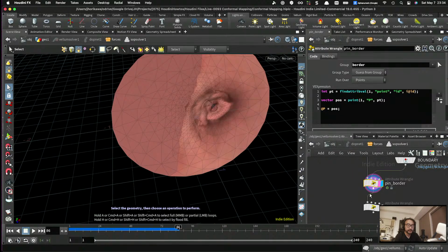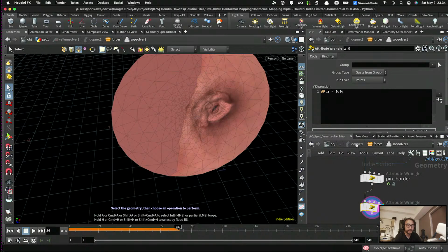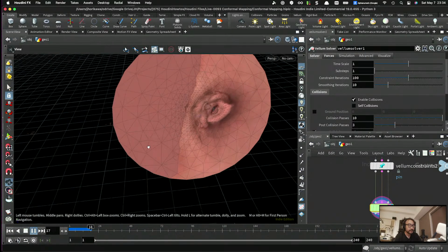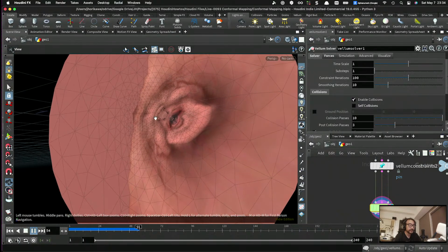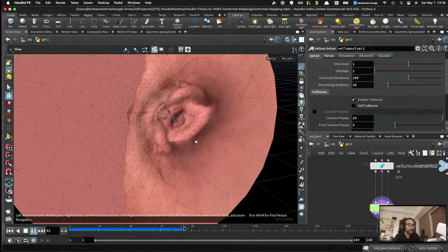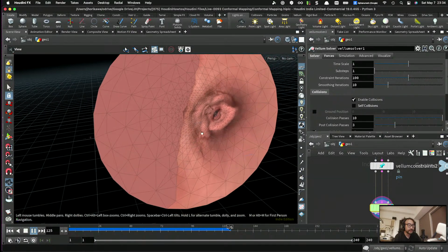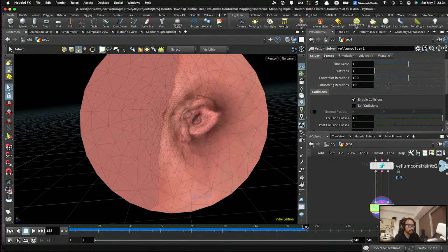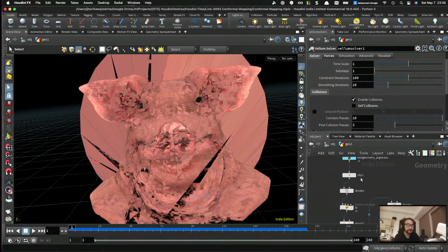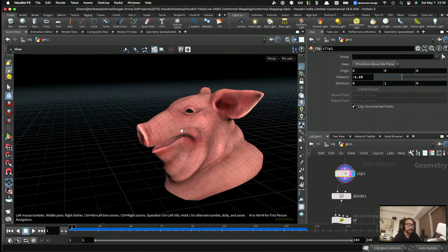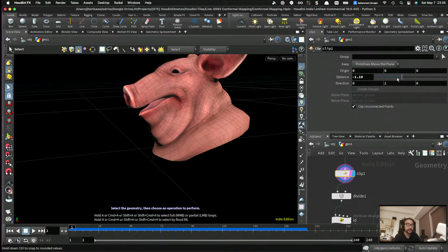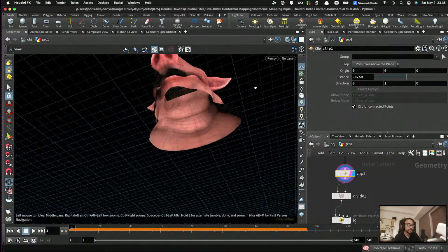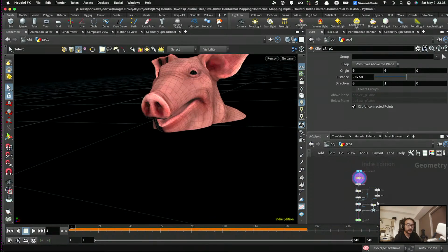And let's go back to the solver, enable z equal to 0 as well. And as a result, you see that I am getting this flattened-out pattern from a three-dimensional geometry, something like that. And it should work for any kind of geometry if you have a single hole. So if I change the clip positions to somewhere around here, it should still work the same. Let's check.